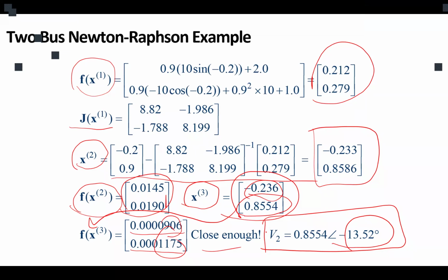Then we learn what the situation is. In each bus, we have P, Q, V, and theta as our variables. Every time we want to analyze, we know two of them and we want to find the other two. So if we know P and Q, we want to find V and theta. Then we use the power balance situation, which is a very basic fundamental rule based on KCL, to find out whether our solution is accurate or not.